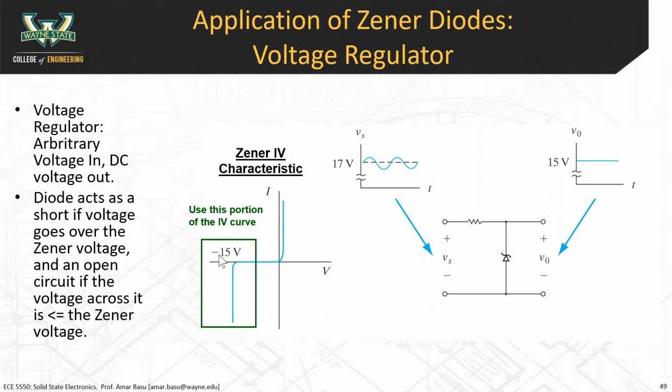We're going to talk about one way of doing it here with the Zener regulator. But the low dropout regulators also have a different type of reference built into it, a reference voltage. The basic concept is this. For the LDOs, the low dropout regulators, they measure the voltage that's coming out of the system. Let's say you want your LDO to work at 3.3 volts.